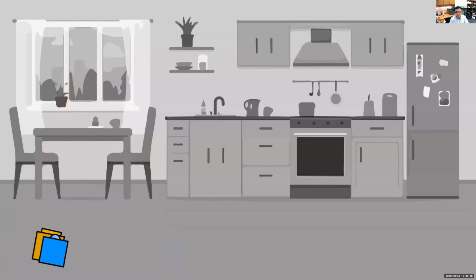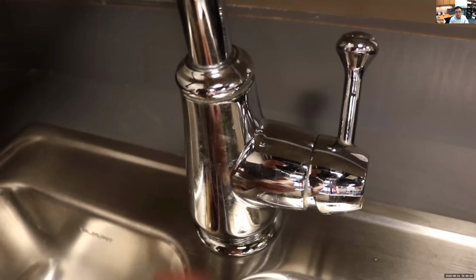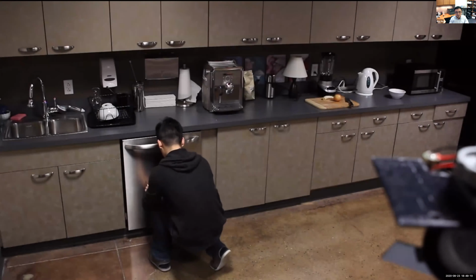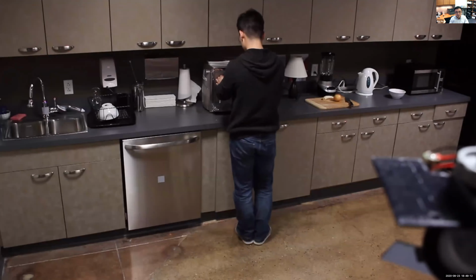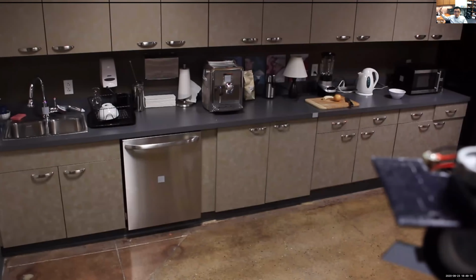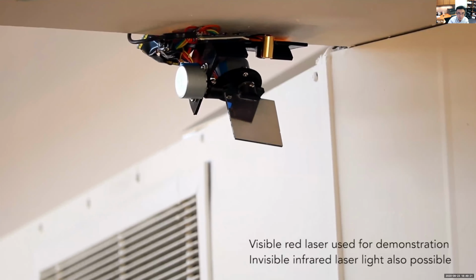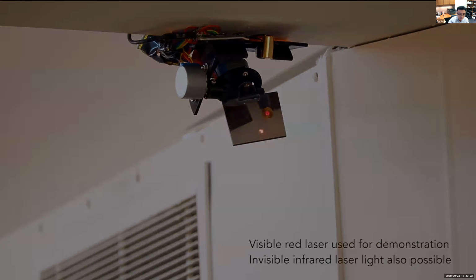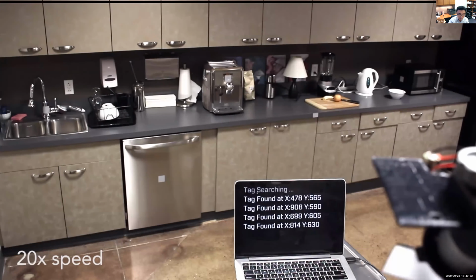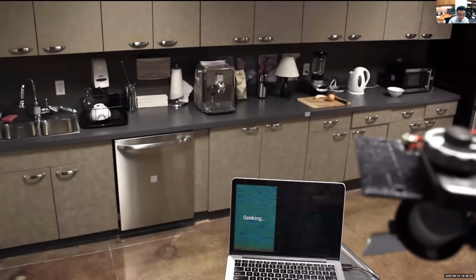Ideally, we want to place the emitter and receiver together in one small sensor package that works at any angle or distance. To achieve this, our system uses small tags made from retroreflective material. These are placed by users onto objects and surfaces they wish to reveal to our system. Only objects that are tagged can be found and sensed. Our system uses a steerable mirror to control the location of sensing. Periodically, our system scans over an environment to find tags. Once tags are found, the system cycles between them to sense the vibrations of their host objects.